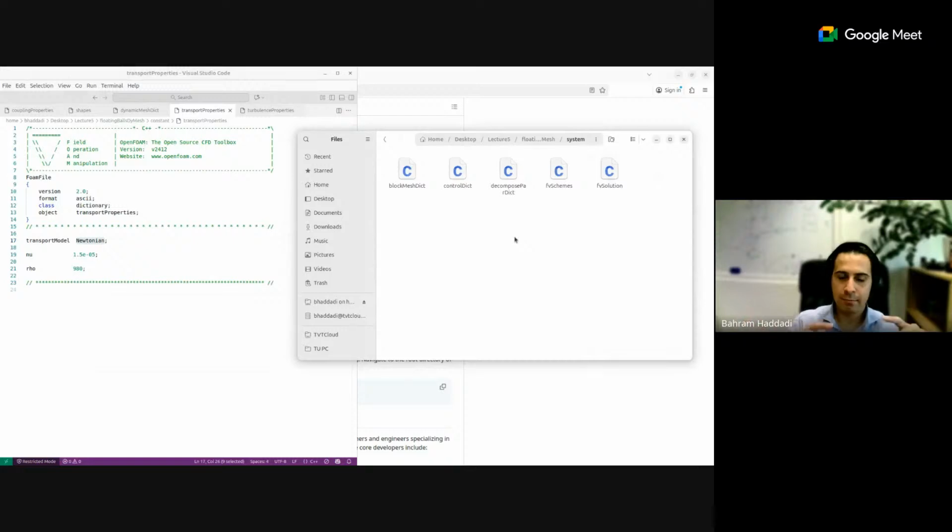Again, we go back to this bold title. The physics should work. So if, for example, the drag model that you're using is for a Newtonian fluid, and you force it with a non-Newtonian fluid, then it might work. But in the best case, it might work, but the results are physically wrong. And in the worst case, it will just crash.